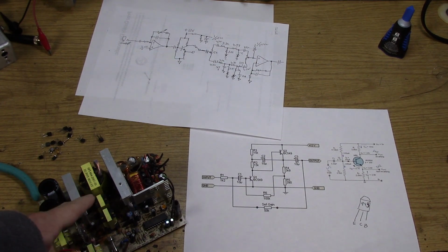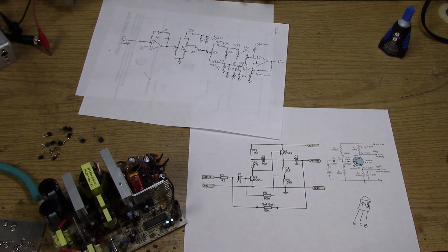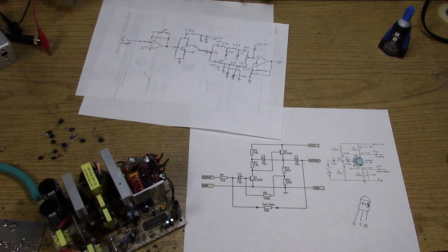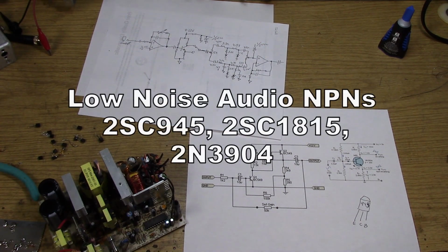Now I'm still working with the ATX power supply as my major source of parts. And there's a lot of bipolar transistors. I've pulled off some of these ATX power supplies. And they're all over the place, but there seems to be several that are used over and over again. The 2SC945 seems to be used a lot. It's a general purpose transistor, low noise, has a pretty high gain bandwidth, has a pretty high FT, and they're all over these ATX supplies. It's a wonderful NPN transistor.